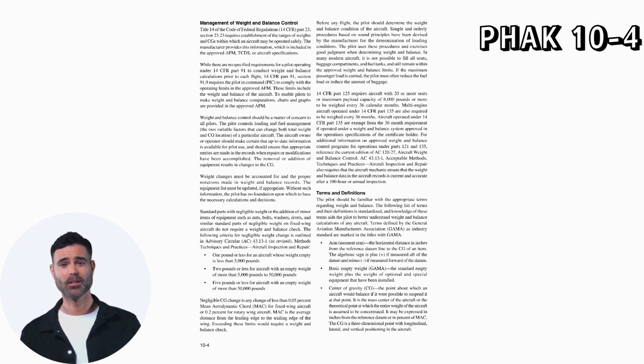For additional information on approved weight and balance control programs for operations under Parts 121 and 135, reference the current edition of AC 120-27, Aircraft Weight and Balance Control. AC 43.13-1, Acceptable Methods, Techniques, and Practices, Aircraft Inspection and Repair also requires that the aircraft mechanic ensure that the weight and balance data in the aircraft records is current and accurate after a 100-hour or annual inspection.